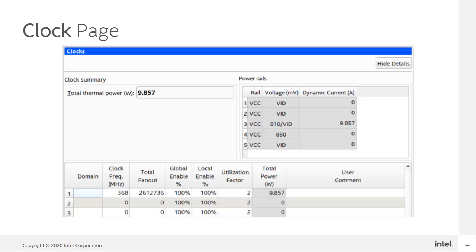The clock network fanout can be obtained from the global and other fast signals summary report in the fitter place stage report. Like RAM and DSP, set the enable active percentages for each clock. Gating an entire clock network, or at least the local part of a clock network driving particular logic array blocks, can have a significant impact on dynamic power usage, since unclocked resources use little to no dynamic power.